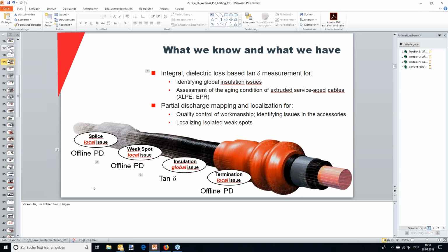I can tell you, up to a few months or years ago, Singapore was the strictest utility when it came to that. If they saw a splice at 500 picocoulomb, they would immediately cut it out, because it's a city-state, a city country, with 6 million plus people. The power needs to be on, no risk taken. I think recently I heard that because of the success of their rigorous testing program, they loosened up a little bit. There was a big study recently in Germany, and a few utility companies participated, and they had numbers like 1,000 picocoulomb, something like that.